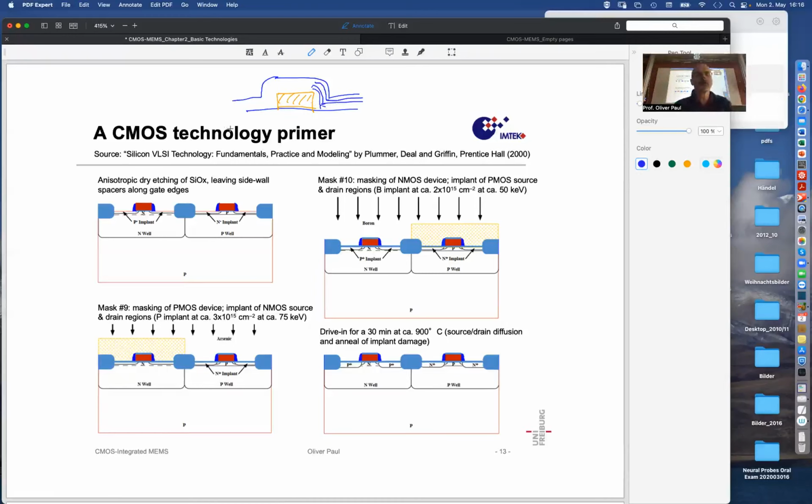So now the removal is vertical. Whatever etchant comes only gnaws at, or etches, removes what it sees. It doesn't go around the corner. So on this side, it just etches down. And here, it etches also down, and then a little bit around these corners. So more and more, and what is left at the end is kind of an image of the structure that you had before.